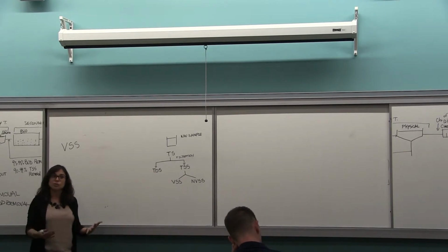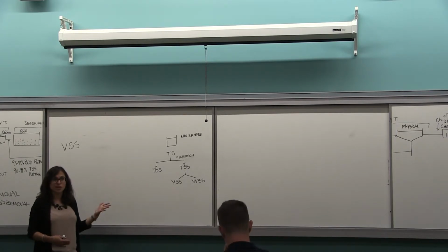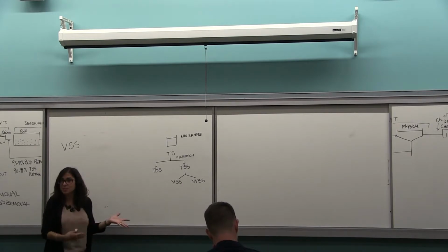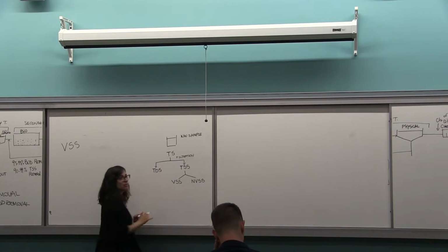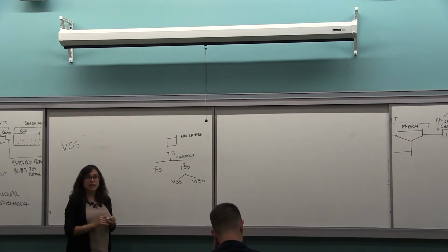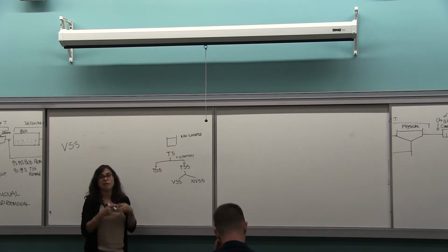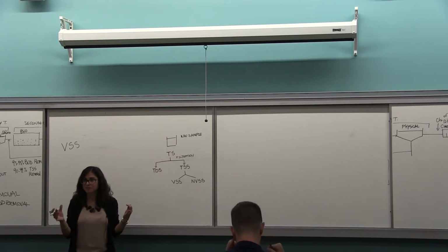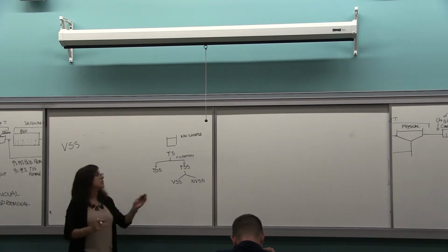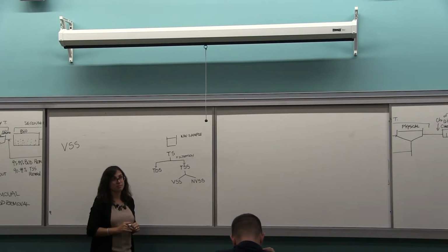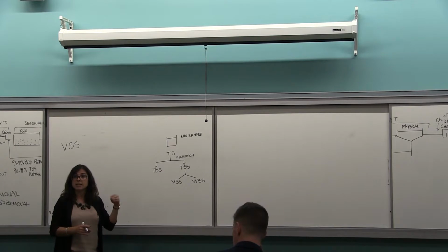So how do we do this procedure? Once you know how volatile suspended solids are determined, it's easy to understand what the data are. So I have my water sample. If I weigh this little container, let all of the water evaporate, measure the residual, and take the difference, I'm going to have the total solids. Not what is asked, right? We want suspended solids.